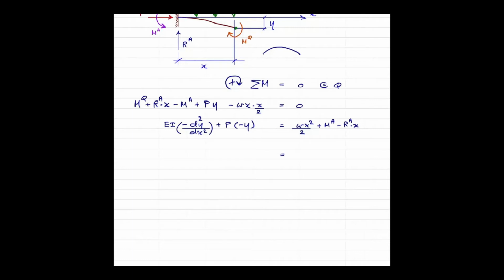So we apply load, we check the damage on the structure, we check the parameters that are progressing with the load, like strain, etc. And we will try to make sure that the test will be able to get everything useful from the test.